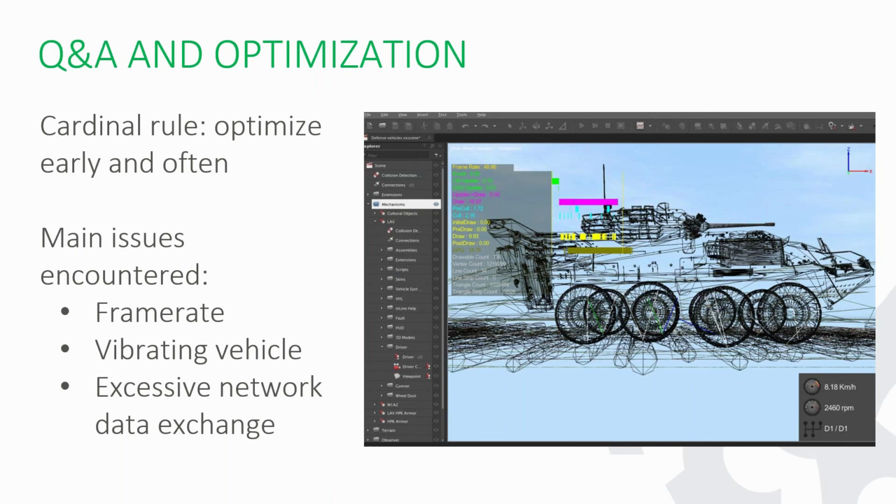So we went back and eliminated every model that could not be seen from the truck. Then we went to the textures and set a number of distances, and every model in those range bands, if you will, had its texture reduced from 2K to 1K, 512, 256, and even smaller as we went farther away. One graphic gallery went from 283 megabytes to 7 megabytes just by doing this cleanup. Frame rate went straight up to 60 FPS.